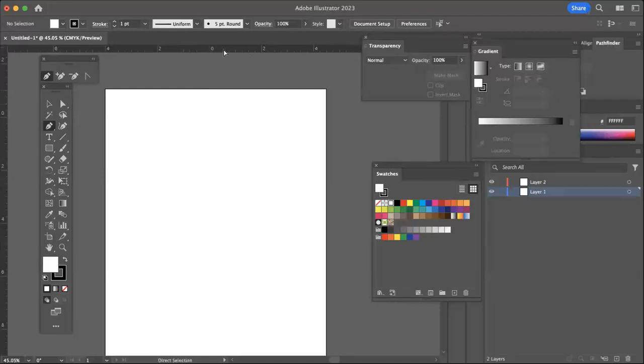So this can be very handy when we are doing our drafting from the center and we want to draft out, as opposed to always drafting from the left-hand side. I'm actually going to leave my 0, 0 where it is. But again, if I wanted to reset it to the top left-hand corner, I could always just click and drag and then leave it there.